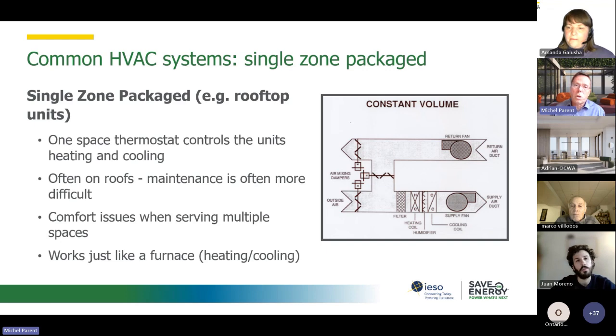And we'll see there's a small equation that I'm going to provide you that most people will know that will tell you the actual percentage of outside air. But always have a look at your dampers, because again, it will be useful later on when you evaluate the impact of potential measures as well as your baseline consumption for the system.